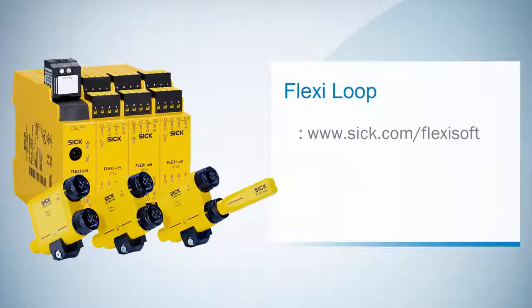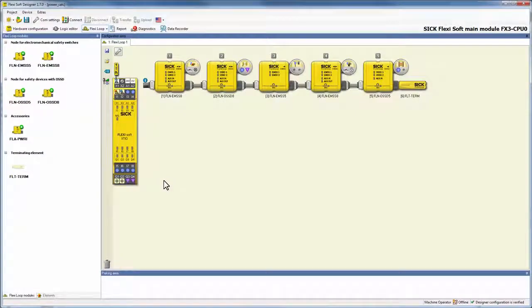sig.com/flexisoft. The power calculation tool helps you decide if you need a power injector for your cascade by calculating the input voltage as well as the currents. Moreover, it helps you to determine where in your loop you can place the injector to achieve the best results considering your machine's circumstances.